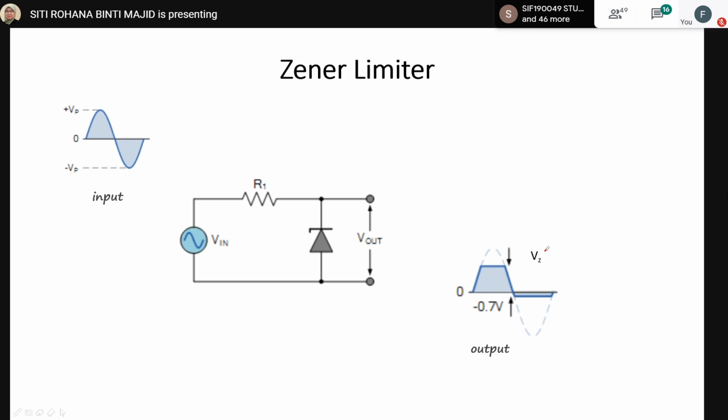Once it flows through a Zener diode, you will notice in the output waveform a square wave signal. So this Zener clipper circuit limits or cuts off the waveform across it, and in waveform shaping circuits we can use a Zener diode to modulate the shape of the waveform.